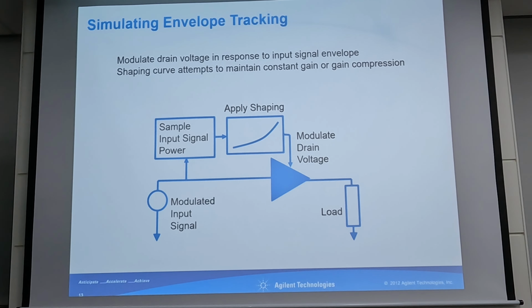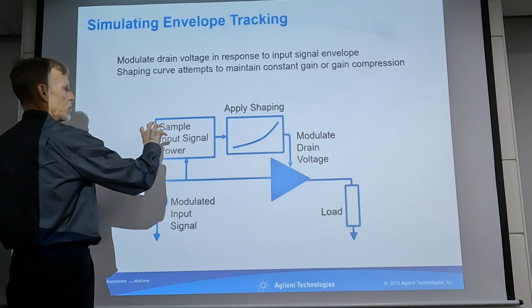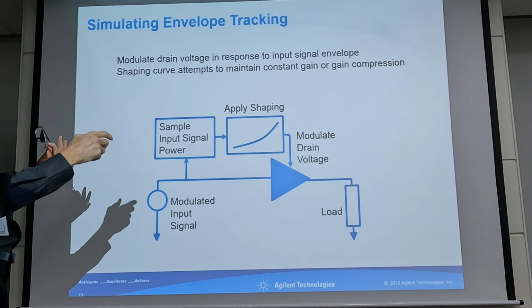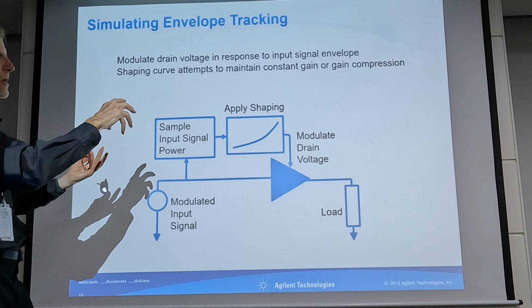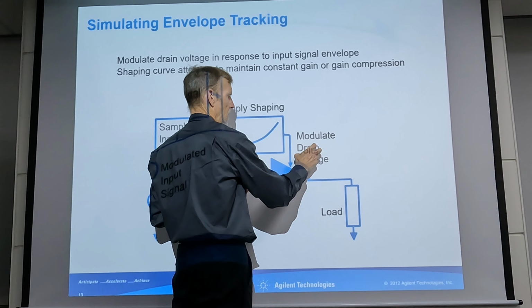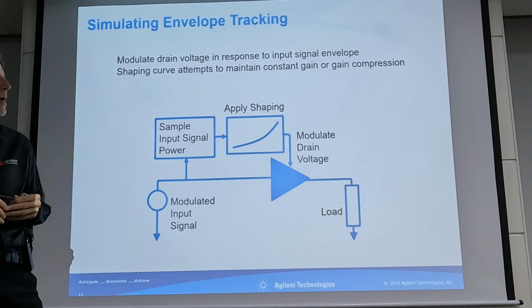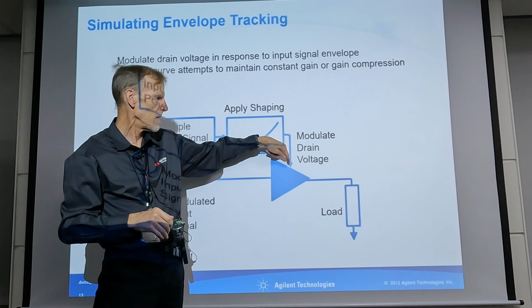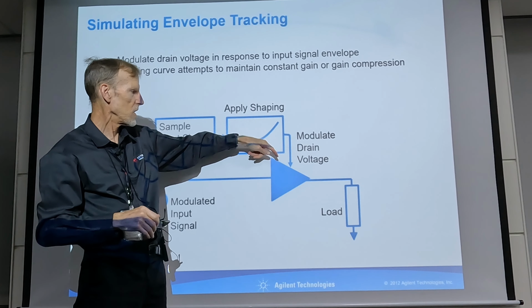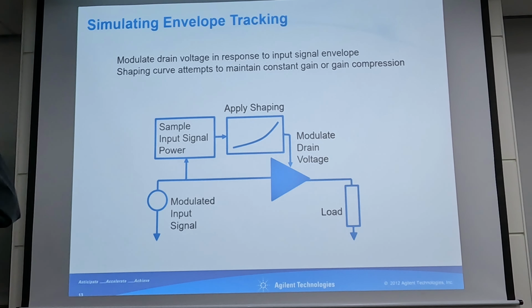But it's like two separate problems. You have some time record of a modulated signal. Maybe your bias modulator is a different simulation, so you're applying the envelope of the input signal to the bias modulator. You get a time domain waveform. It has some distortion because the bias modulator isn't ideal, and so you can read in the distorted time domain signal and apply it in a separate simulation along with the modulated signal and see what the results are. So that's possible to do.